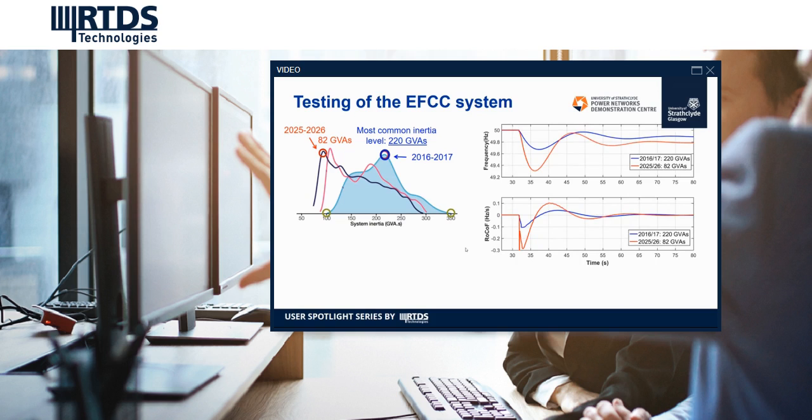If we have a 1 gigawatt loss of generation in the system, for 220 GVAs, we typically see a frequency nadir around 49.7. But if the value decreases to 82 GVAs, we will see a frequency nadir below 49.4 if no action is taken. Obviously, we will see a much higher RoCoF. Now, let's have a look at